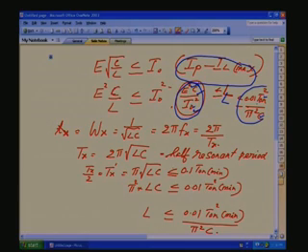Then the upper range we found out from the minimum resonant period. That should be much less than the T on duty cycle minimum of the circuit. From this we can find out the L and C, and the commutation is complete. So, with this force commutation, we are only talking about the DC to DC converter. Just to introduce the DC to DC converter, to introduce this commutation, a very widely used, popular commutation circuit.